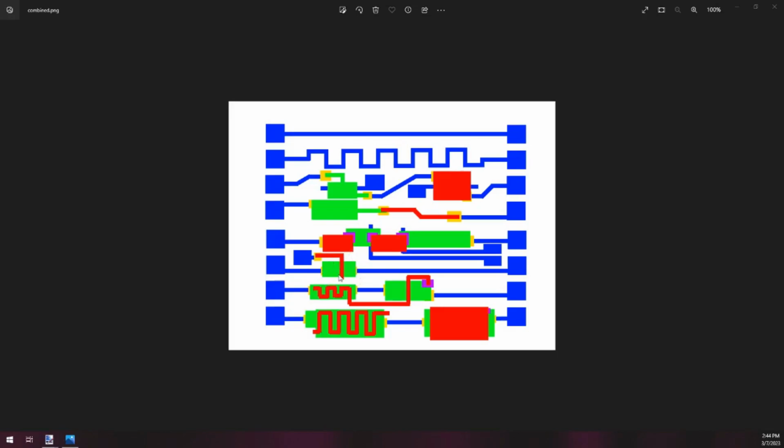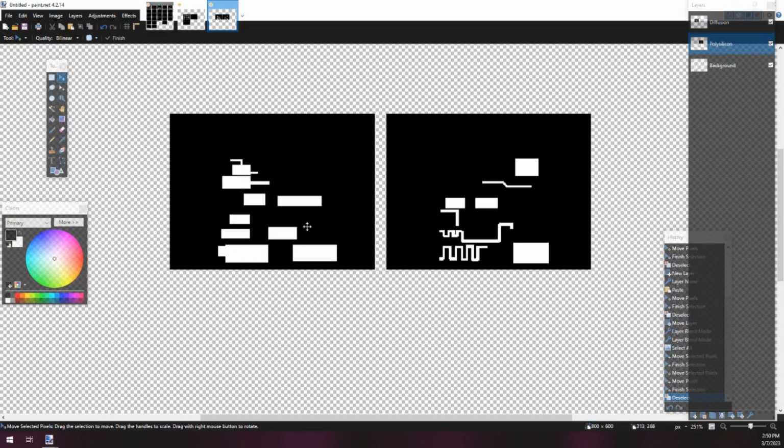I've said it already, but these transistors are basically made of a diffusion layer that's overlapped by a polysilicon layer. Now, that makes sense to you and I. We see the polysilicon passing over. We think these are three separate circuits. But the computer sees the diffusion layer as one solid chunk of diffusion material, so it could potentially see that as one solid circuit, but it doesn't. The trick then is to block out any parts of the image we don't want turned into a wire mask before that happens. And we can do that.